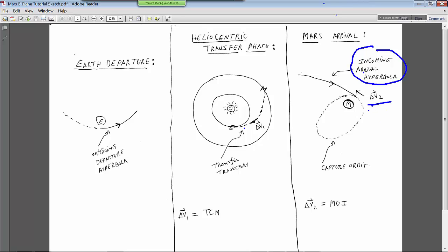So it's going to be a 2 targeting routine in GMAT. The first targeter will target B-plane components to get close to Mars, and then once we're close to Mars at Mars periapsis, we'll come into the second targeter, in which we'll perform MOI, Mars orbit insertion, and then capture about Mars, and we'll orbit around Mars for about 1 day or so. So this is pretty much a summary of what we're gonna do.